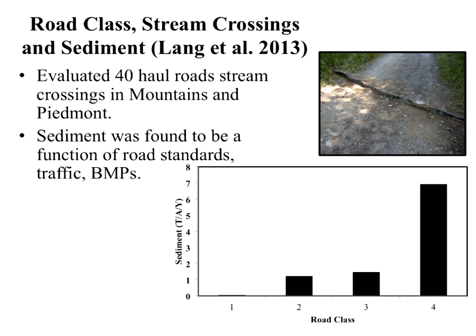Now, what he's looking at is he's particularly focusing on stream crossings with this. The thing to keep in mind is that when you have a Class 4 road, you may be satisfied with a Class 4 road, but at that particular spot, at that stream crossing, we might choose to go more towards the standards of a Class 2 road or a Class 1 road. So again, you might get a bigger bang for your buck by spending your effort at that stream crossing.